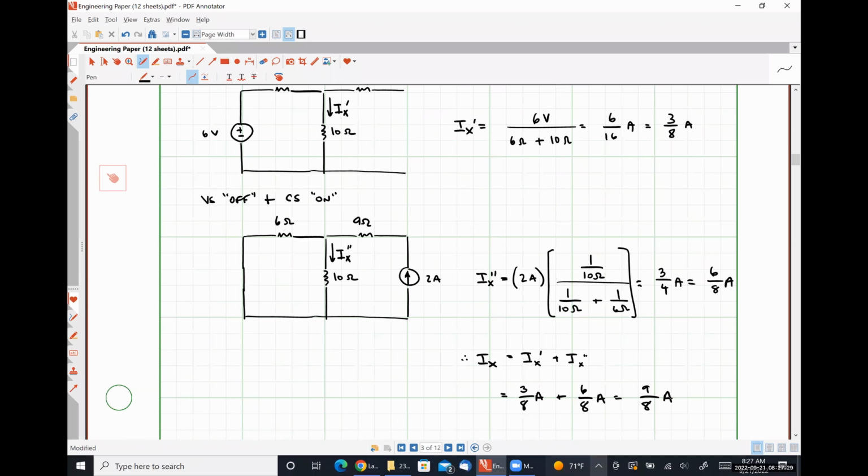All 2 amps of current flows through the 9 ohm resistor and then splits, right? So it doesn't split until after it's through the 9 ohm resistor. This is the additivity principle. And this particular circuit containing voltage sources, current sources, and resistors satisfies the additivity principle, okay? Now we are going to talk about the homogeneity or scaling principle.